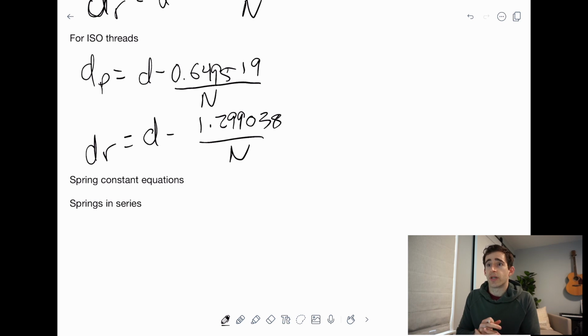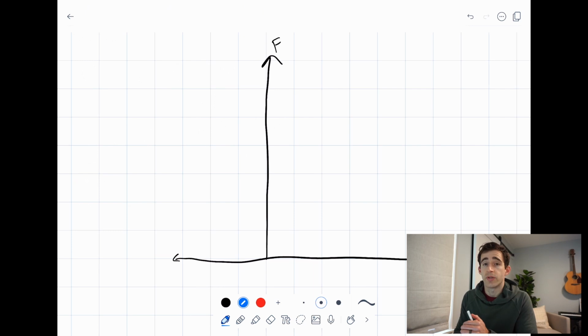This works by ensuring that when the applied load is less than the preload, it works to unload the joined material rather than apply load to the bolt. To understand this, let's think about the joint in terms of material stiffness represented by spring constants K. During preloading, the bolt is stretched and the clamp material is compressed.